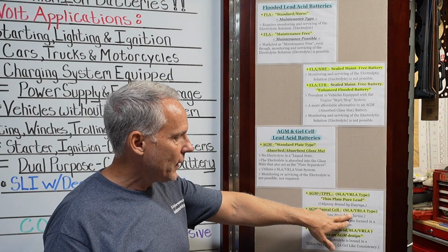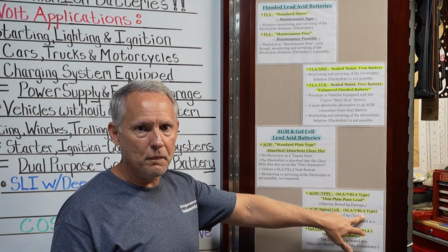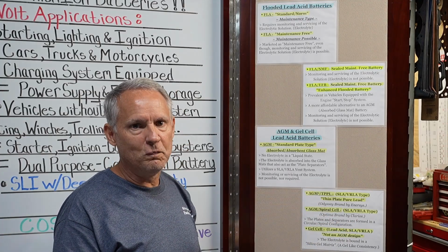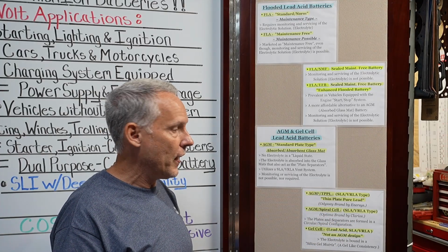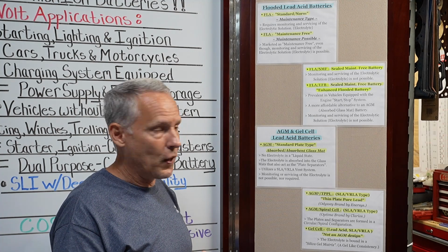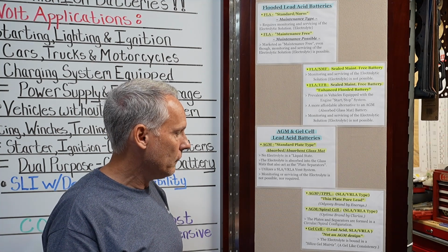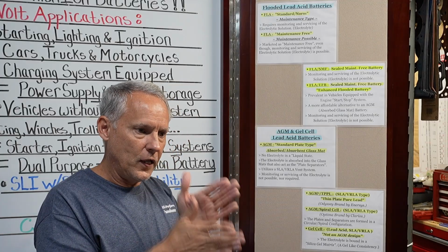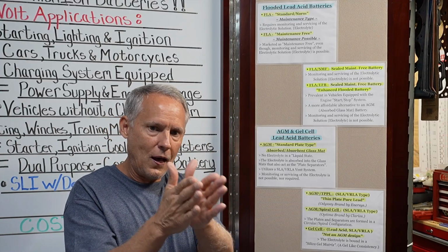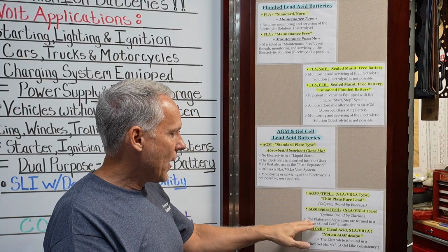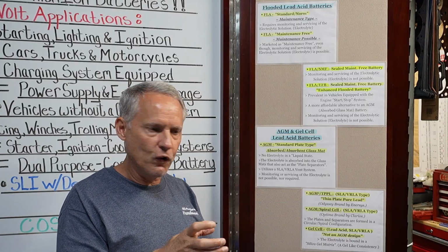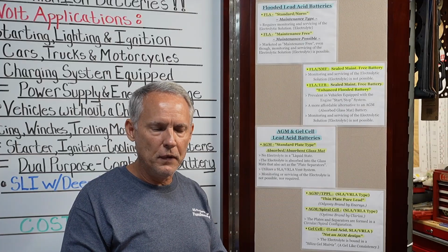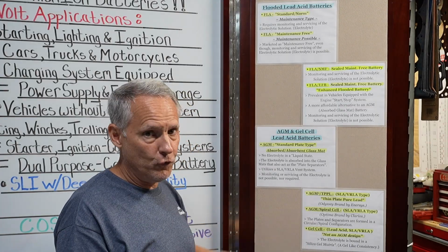That's also a sealed lead acid, VRLA type vent system battery. Optima brand, and that's made nowadays by Clarios. It used to be made by Johnson Controls. They were bought out by Clarios, so now it's Optima brand by Clarios. The plates and separators, instead of being standard plate type that just hang side by side like in parallel, they're actually in a spiral or circular configuration. So the plates and separators are formed in a circular or spiral configuration. Right? So that's what makes it kind of unique.